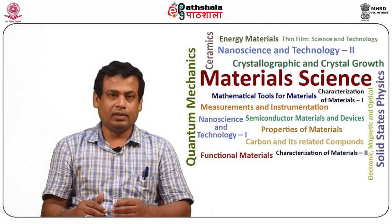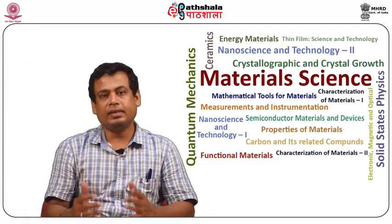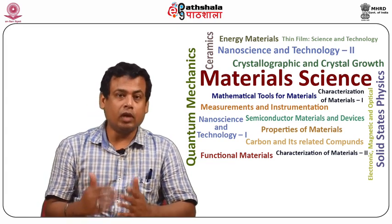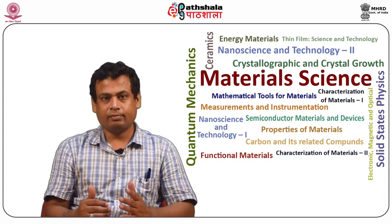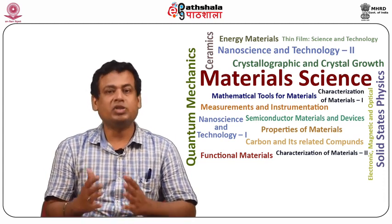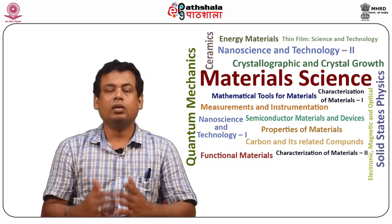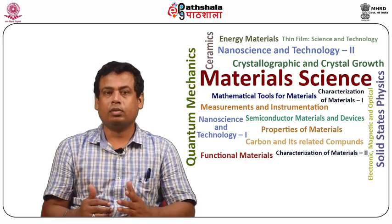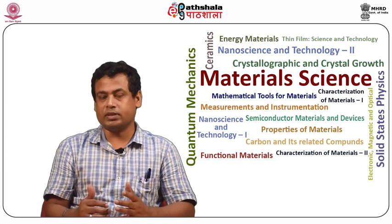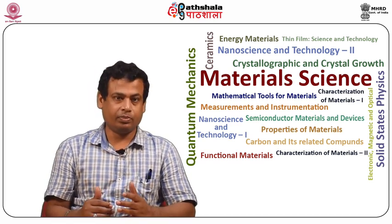Electron beam lithography is a maskless technology developed in the 1950s. The aim is to create nanometer scale structures in the resist that can subsequently be transferred to the substrate material, and the resist is used as a patterned mask for semiconductor processing during the microfabrication process.